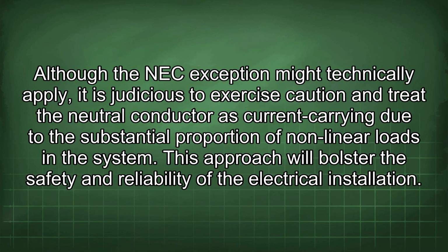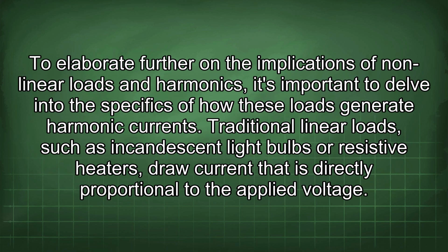Although the NEC exception might technically apply, it is judicious to exercise caution and treat the neutral conductor as current-carrying due to the substantial proportion of nonlinear loads in the system. This approach will bolster the safety and reliability of the electrical installation. To elaborate further on the implications of nonlinear loads and harmonics, it's important to delve into the specifics of how these loads generate harmonic currents.